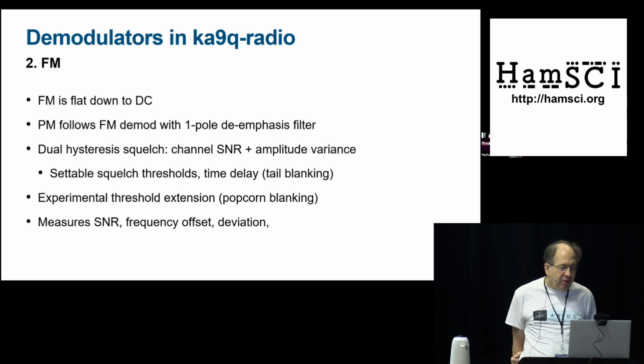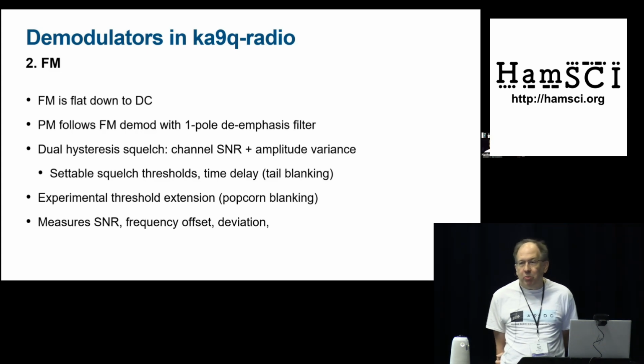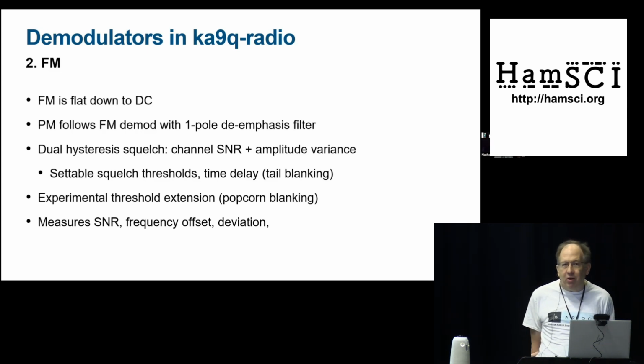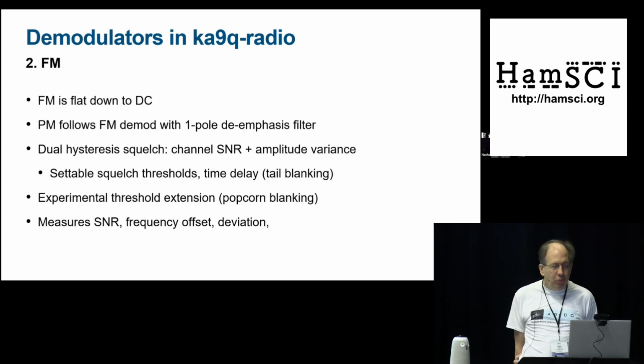And it measures signal-to-noise ratio, which is how the squelch works. The squelch works from first principles. It actually computes the SNR and says, okay, is it above this threshold or below that threshold, whether to open or close the squelch.